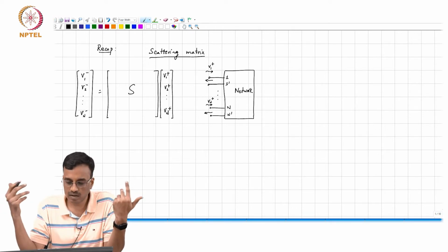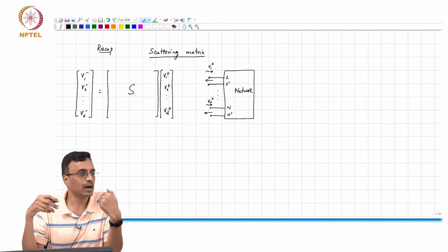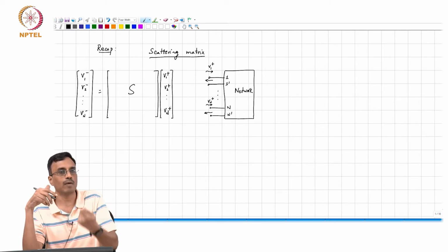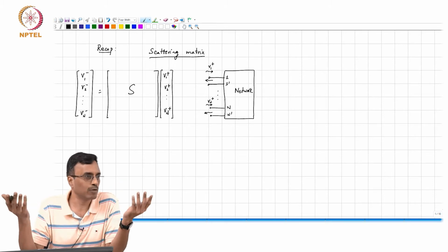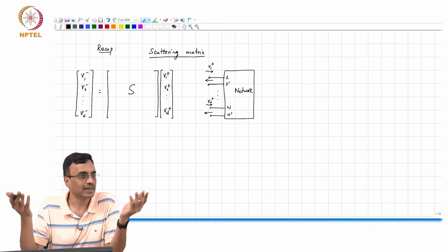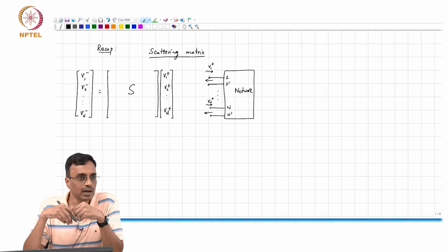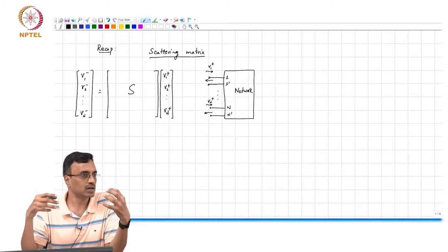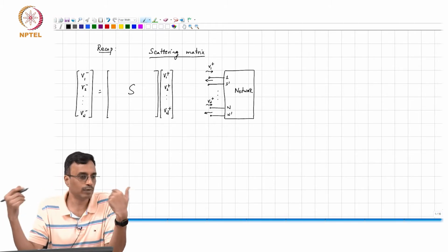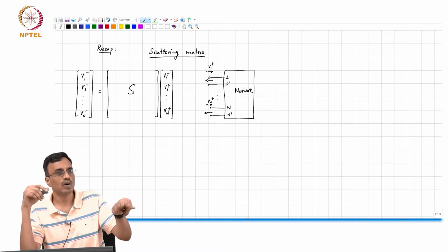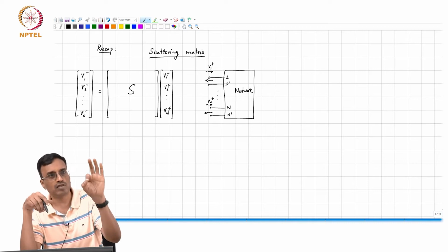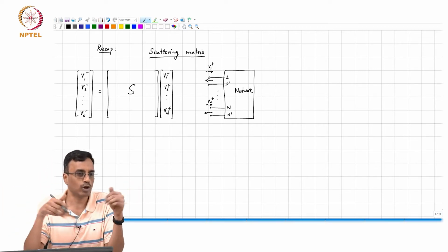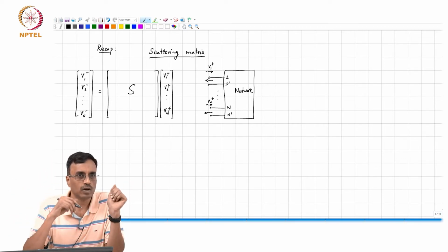Therefore the real world difficulty of having to run a cable from the port to the termination, or to the measurement equipment for that matter, goes away, and you are now able to measure. So terminating the cable with 50 ohms is equivalent to terminating the ports with 50 ohms at the location of the port, even though the actual port may be a mile away from your terminal.